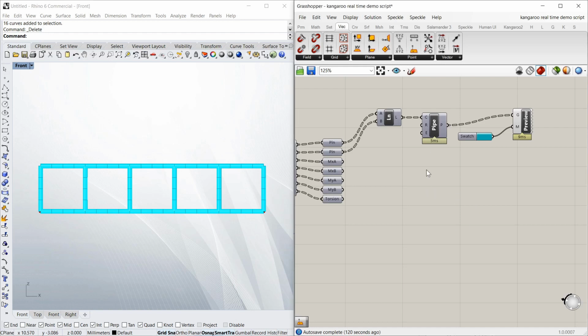Okay, so now we can start drawing the moments, and to do that we're going to use this component which is point oriented, and we can use the information we've already got in these planes rather than just the point information, because it's got a vector in it as well. So this allows us to draw a point in a plane, so we just have to give it how far in its internal coordinates rather than the universal X, Y, Z. So the plane's already set up for us. We just need to give it a value.